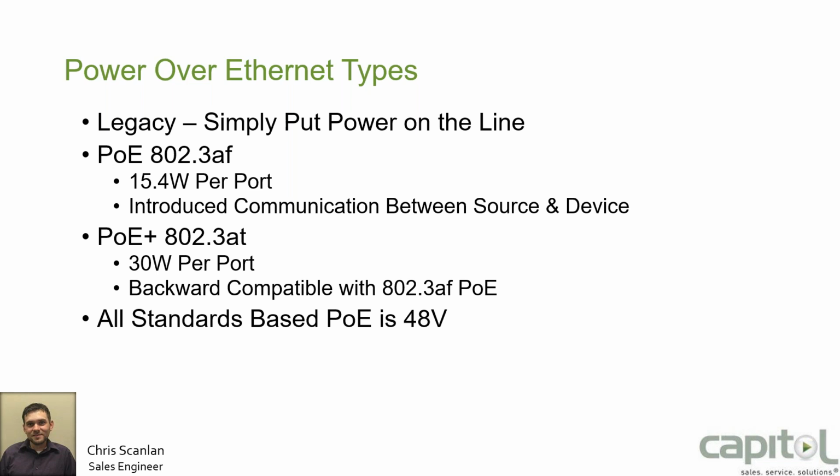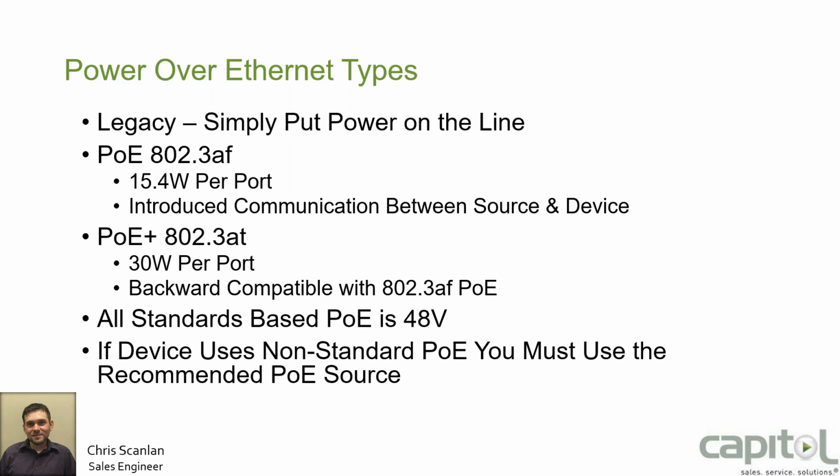Also, all standard PoE is based on 48 volts. If you find a device that's an older camera or something that takes, let's say, 12 volts or 24 volts PoE, that's not standard. You do not want to power that from a standard PoE injector or the switch. You must use the PoE source that comes with that device or what's recommended for that device.